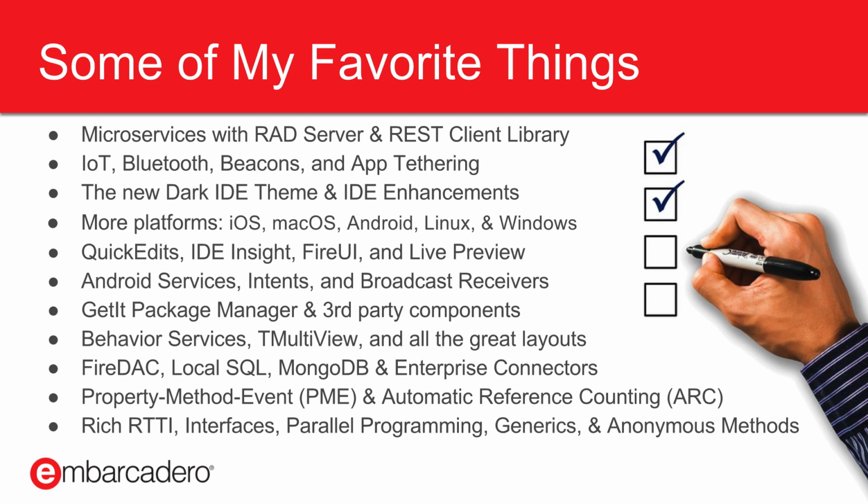They connect most of them via Bluetooth LE or Bluetooth Smart, which is the latest part of the Bluetooth 4.0 spec that is great for talking to these devices. It's low energy, LE, which is great for these small devices that you're sending small amounts of data to. We also have support for Bluetooth Classic, which is what you use when you're connected to your car or to your smartphone and you're sending music back and forth. It's that high bandwidth, longer range, but it uses more power. So LE uses less power. Bluetooth Classic is more of a serial connection where you're just sending data back and forth.